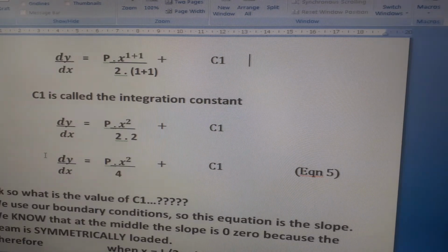So if you had a beam that deflected 10 centimeters, and that was dy, and the beam was 100 centimeters long, then dy over dx would be 10 over 100. So that's also the gradient of the slope. There's a good point in that I do not believe that dy over dx is an angle, it's a ratio.